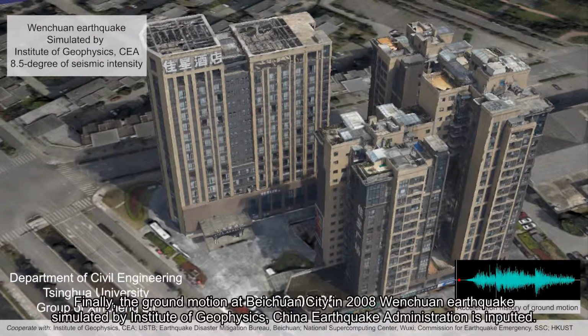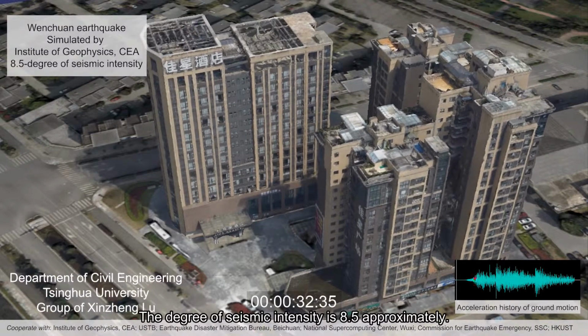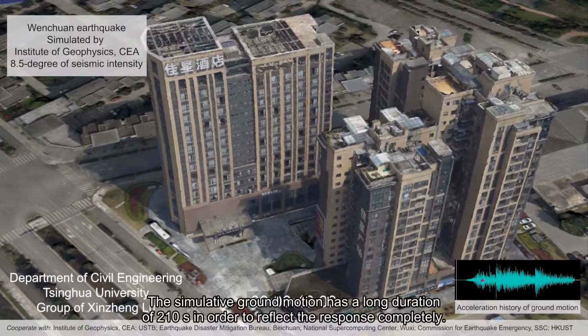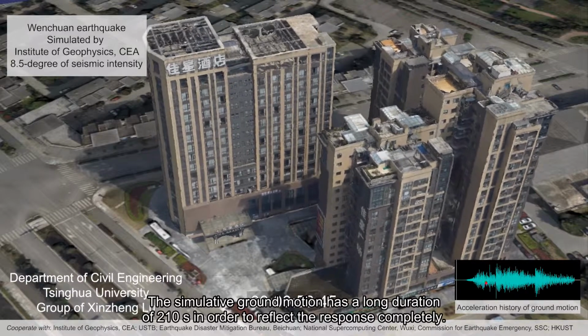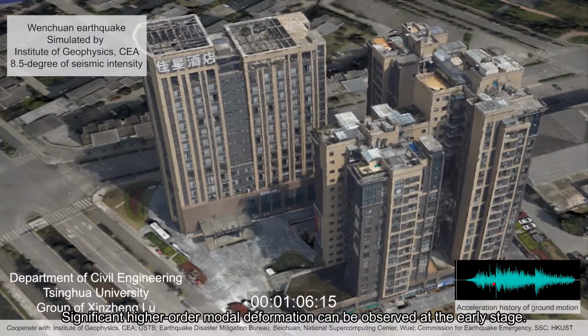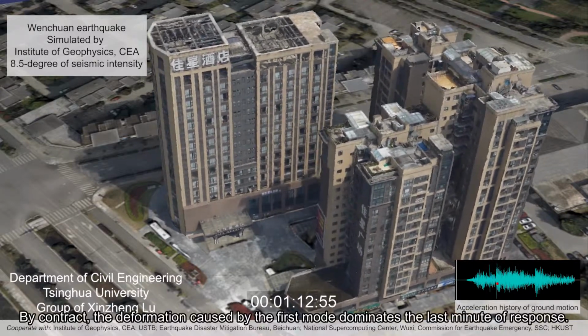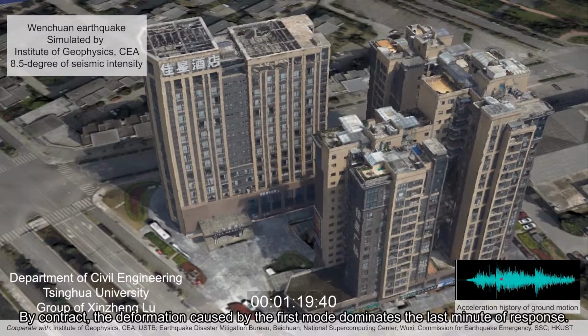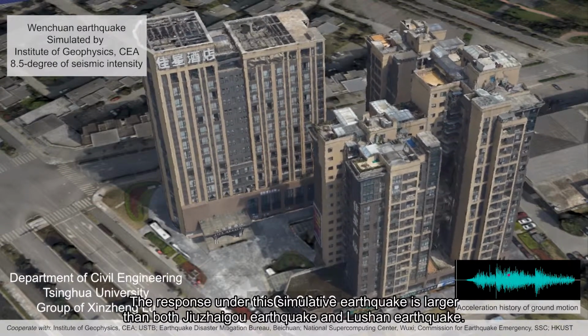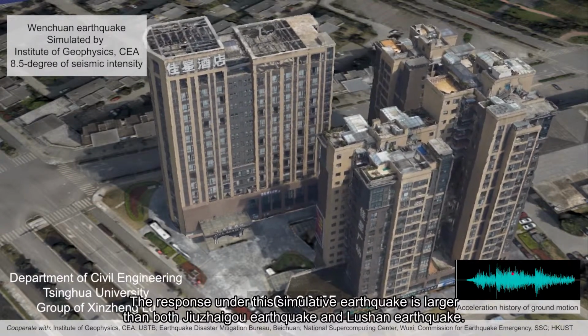Finally, the ground motion at Beichuan City in the 2008 Wenchuan earthquake, simulated by the Institute of Geophysics, China Earthquake Administration, is inputted. The degree of seismic intensity is approximately 8.5. The simulated ground motion has a long duration of 210 seconds in order to reflect the response completely. Significant higher order modal deformation can be observed at the early stage. By contrast, the deformation caused by the first mode dominates the last minute of response. The response under this simulated earthquake is larger than both the Zhujiang earthquake and the Lushan earthquake.